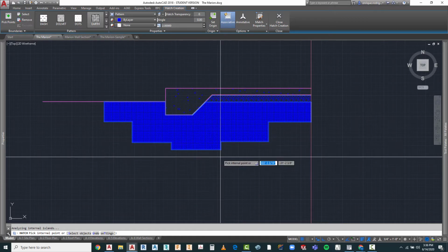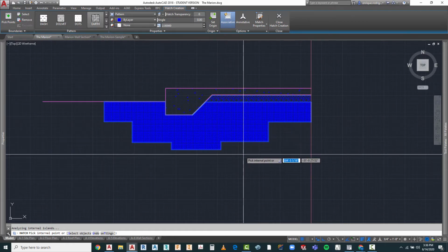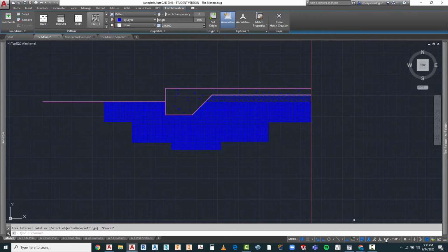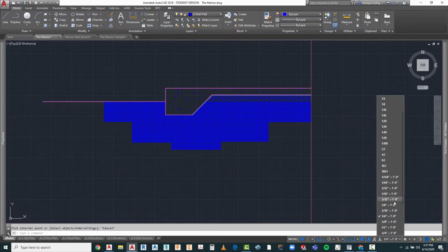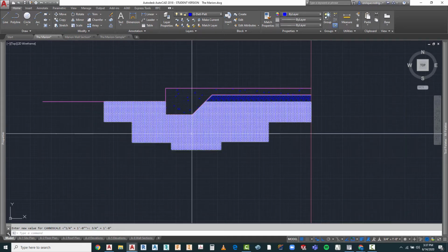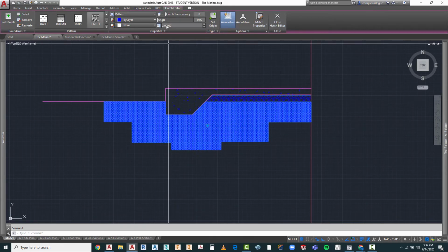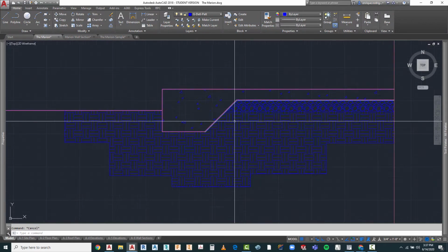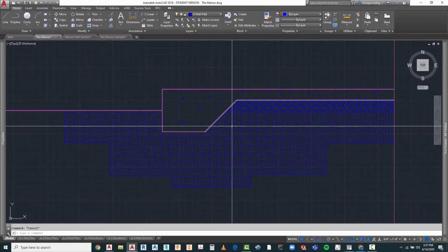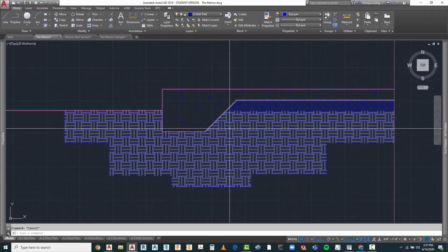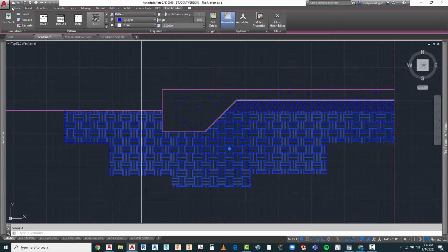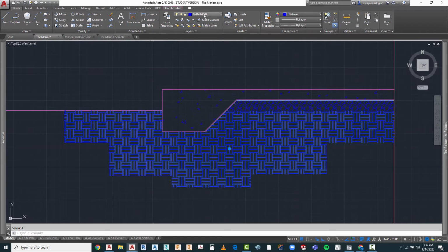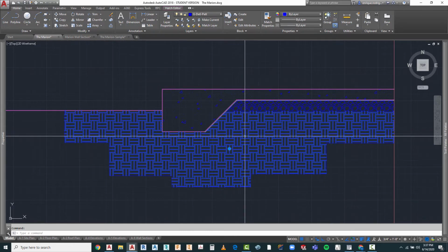And once again, it looks like it's coming in at too small of a scale. What we are going to do with our section here is show it at a much bigger scale than we show our floor plans and so on. So what we need to do is adjust this scale. Let's try 12 with this one. That doesn't look bad. So we can also change these later on. The one thing about this is that we are definitely going to want it to be in our G detail pattern layer because of the thickness of the lines that are going to be shown in there.